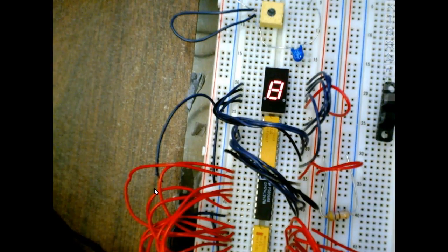Okay, so that was which step? It doesn't tell us to do that, right? Yeah, switch 3 will be closed. Open switch 5. Switch 3 would be closed. Then it's asking to close the RBO input. That does nothing because that's an output. The pin they want is RBI, so let's change B to RBI. They don't ask for the RBI input anywhere, do they? So step B, let's change that to RBI, and I'll make a correction on that.